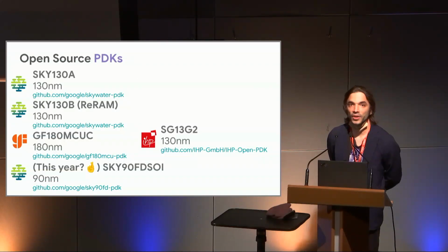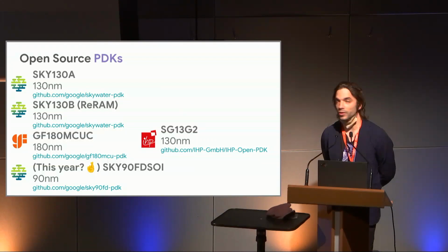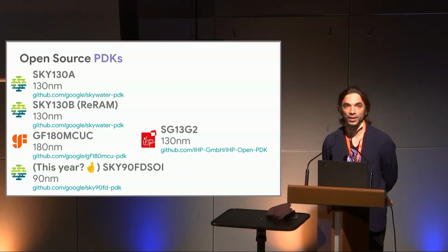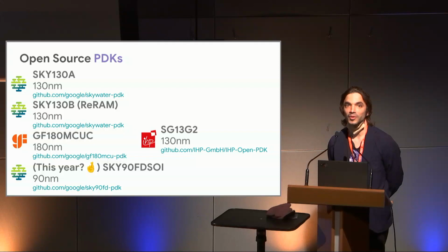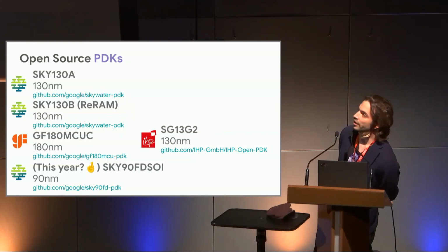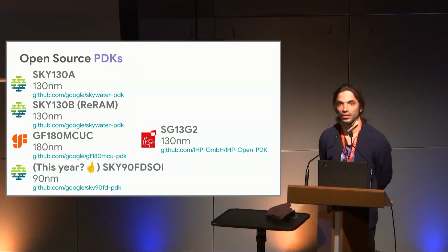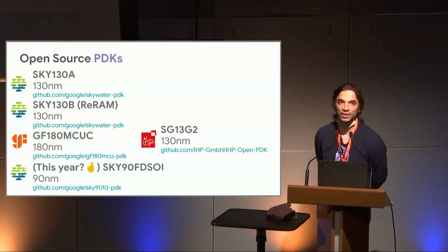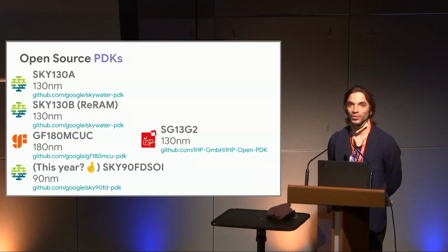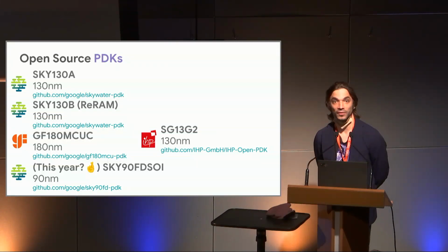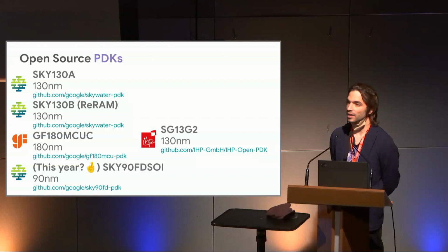So the first thing that we've done is that we've partnered with some of the foundries, like Skywater and GlobalFoundries, to convince them to open source the PDK for their older technology. So those are 130 nanometer and 180 nanometer technology. Those were the things where the first Pentiums were built. But those are totally fine to learn and totally fine to experiment with, and totally fine to prototype for startups for IoT products.